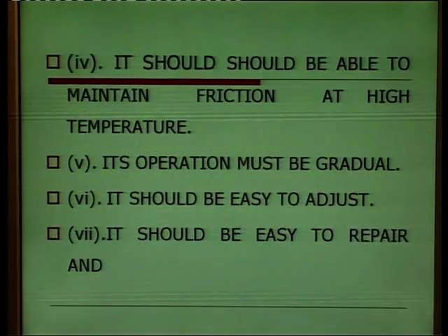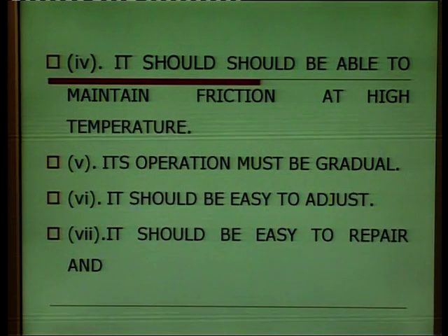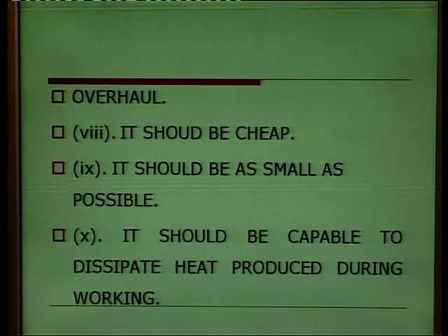Number four, it should be able to maintain friction at high temperature as well as low temperature. Number five, its operation must be gradual. Number six, it should be easy to adjust. Number seven, it should be easy to repair and overhaul.